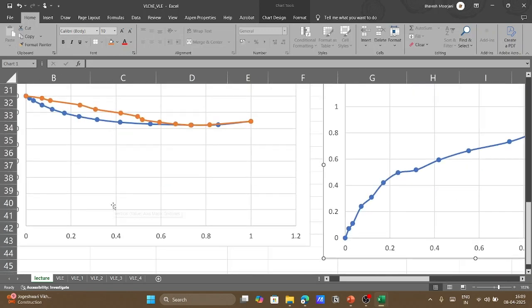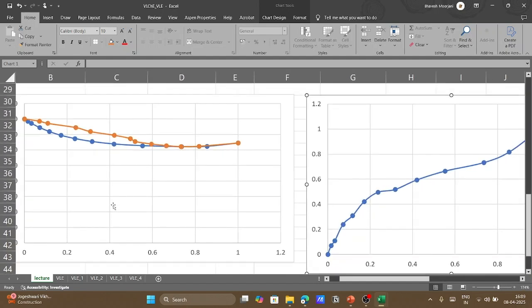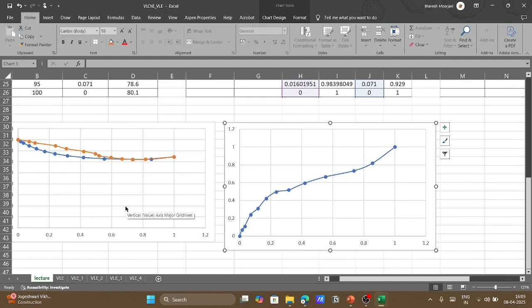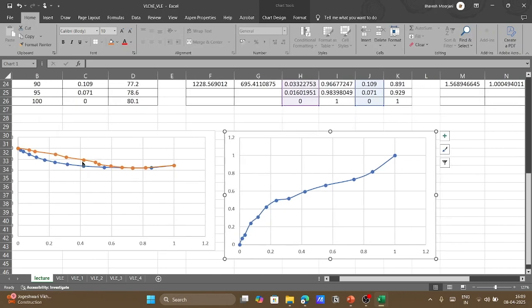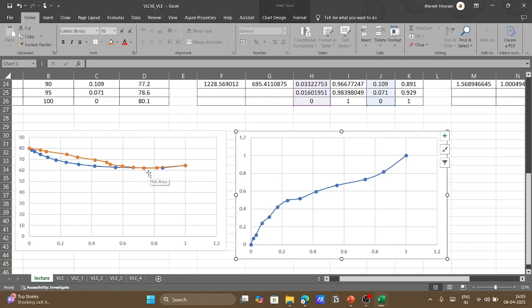So this is how our TXY diagram looks. Again, you can see that at a lower mole fraction of A, we get a two-phase separation. We get the in-between region where both vapor and liquid will coexist. But after 0.7 mole fraction of A, the vapor and liquid mole fraction lines, Ty and Tx, are almost coinciding. That means at these conditions, for 1 atmospheric pressure, if we have this composition and lie in this particular region, the separation of A and B won't be possible.